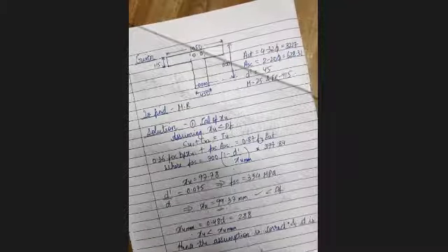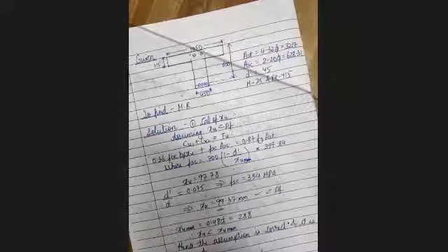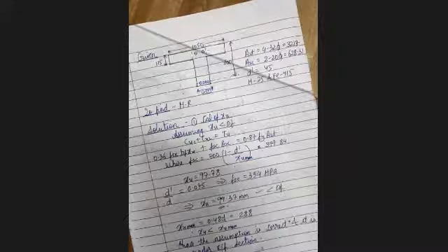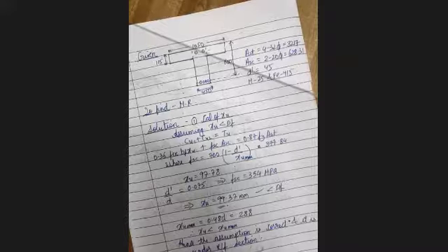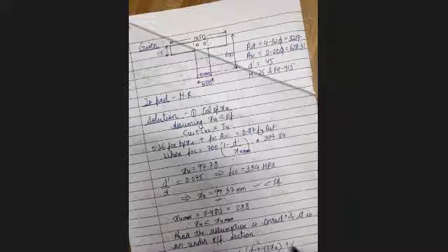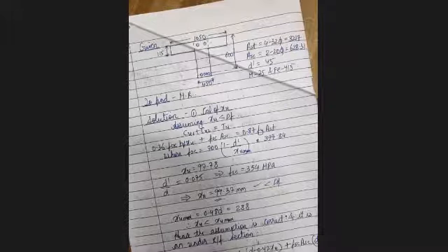And it is an under reinforced section. So therefore, we can find out MR now. So MR is CU1 into lever arm 1 plus CU2 into lever arm 2. So 0.36 FCK B into XU into D minus 0.42 XU, plus FSC into ASC into D minus D dash. So this value, everyone getting 647?